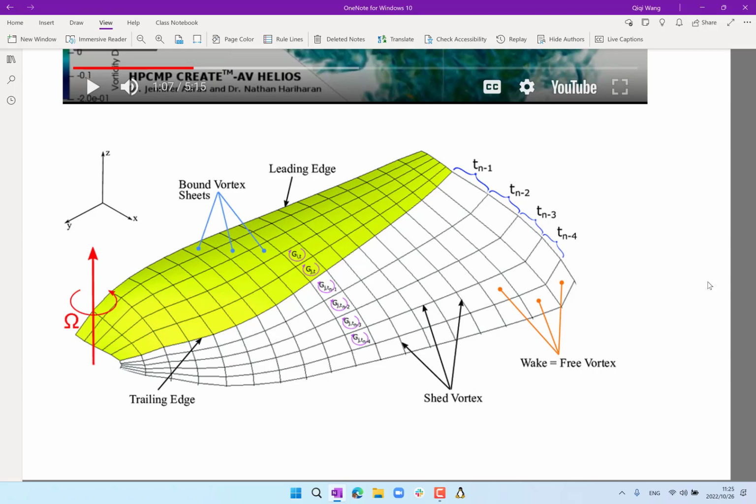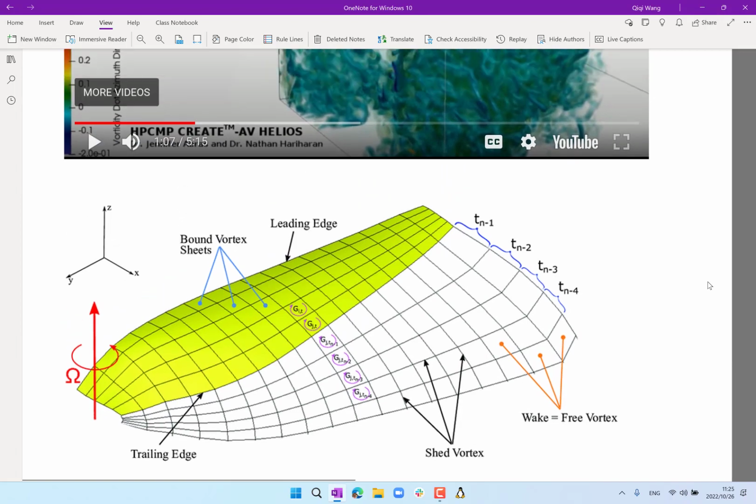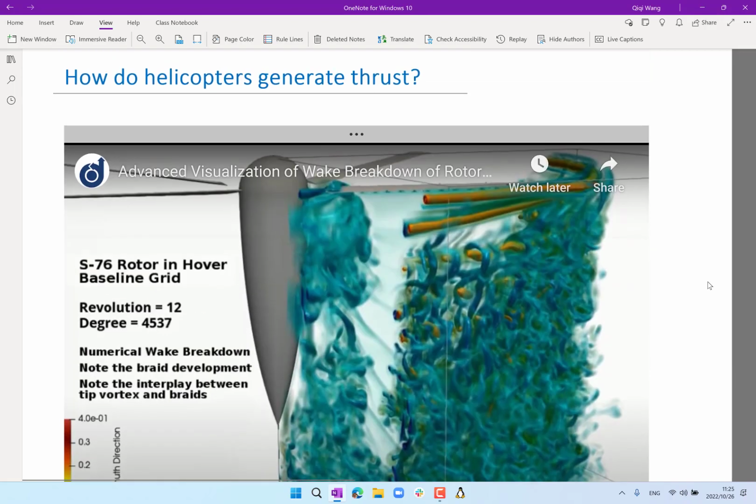So the vortex ring here would not cancel with the vortex ring here, even in this dimension, right? So you would get actually a continuous sheet of differently strengthed vortices. All right, so this is really the extent to which the vortex lattice method can be used.